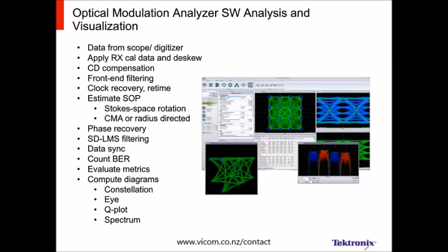So it's basically fixing everything. When you turn on these adaptive filters, the constant modulus algorithm is one of them. The symbol-directed or decision-directed least mean square is another example. When you turn these on, it's going to be more difficult to get agreement between the suppliers.